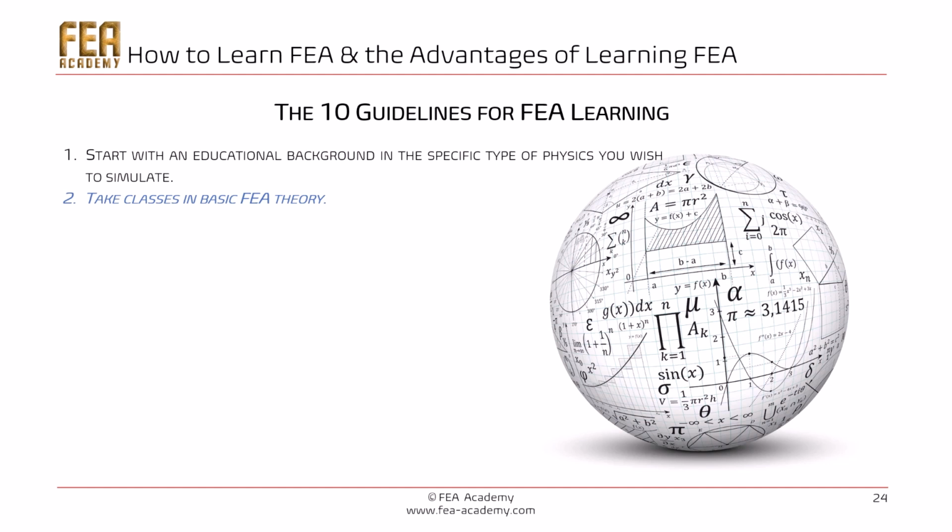For sure, you will not develop an FEA software or a new element, but as an engineer, learning the basic theory of FEA will permit you to understand four things. First, how the stiffness matrices are computed for various topologies of elements, how the global stiffness matrix of your system is assembled, how the solver computes the equations to obtain the primary variables, the displacements in mechanical structural analysis, for example, and how the solver computes the secondary variables, the forces, the stresses, the strains.